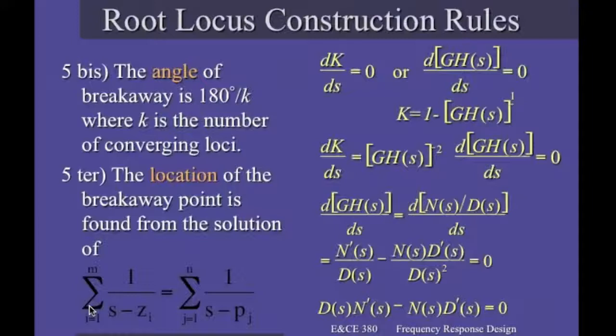Evans demonstrated that this equation can be obtained by setting k as a parameter depending on s, because k is actually changing when we plot the locus. And as a consequence, the closed loop transfer function poles are assuming different values for s as long as k is changed.